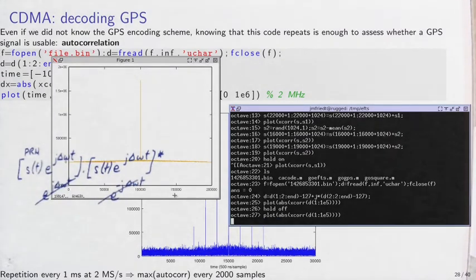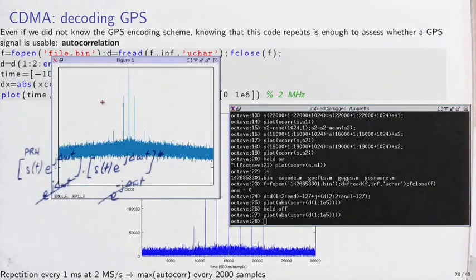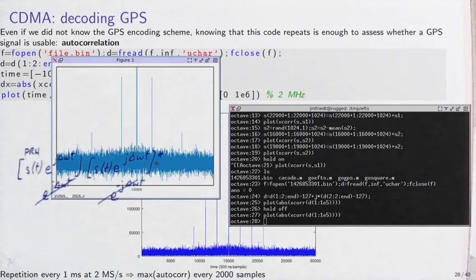So here is the autocorrelation of the signal, and if I look closely close to the carrier at 100,000, I see these side lobes, side correlation lobes. I see here that the center is at 100,000 because I'm sweeping 100,000 long samples, so that I have a 200,000 output